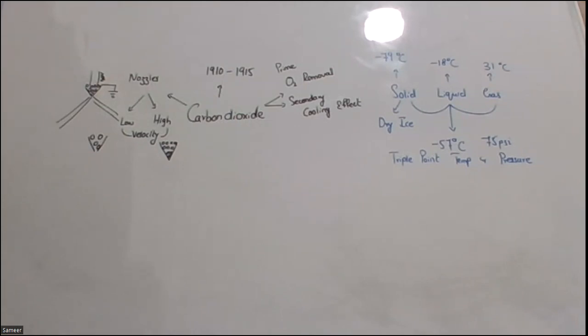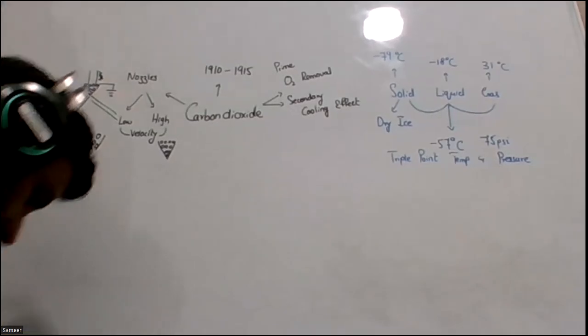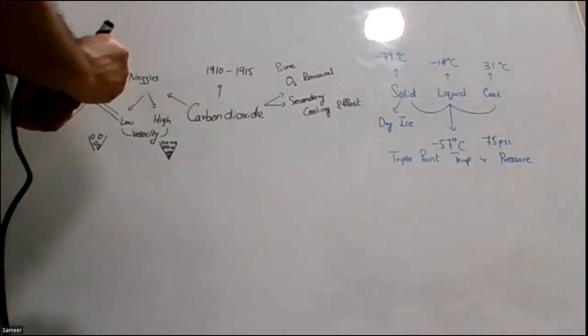So usually we have nozzles of two capabilities, high velocity and low velocity nozzles, for carbon dioxide systems. Whenever a carbon dioxide system is applied in an area, it removes oxygen, we have discussed, right? But what is the percentage of carbon dioxide that is much more dangerous for us? Carbon dioxide in specific areas holds a specific percentage.